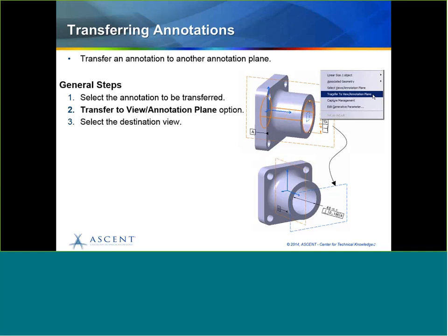One thing to keep in mind with this tool, of course, is the destination plane, the plane that you want to move that annotation to. It has to exist before you try to do the transfer. So simply make or create that annotation plane and then do the transfer.